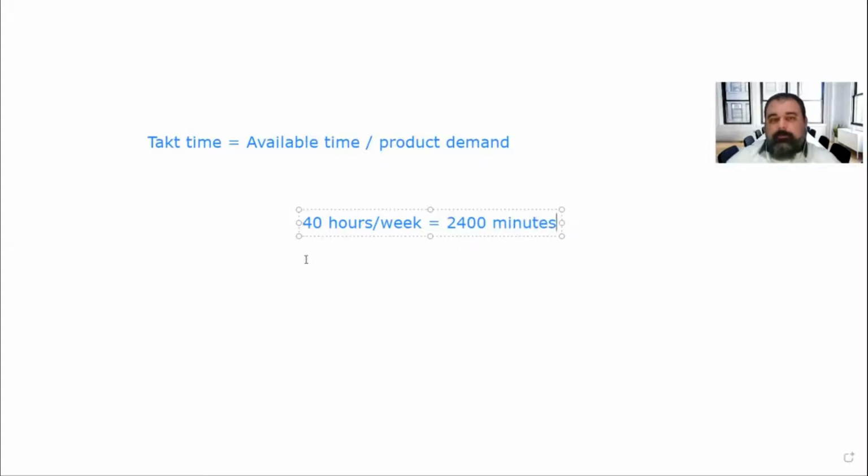And if your product demand is about 1,000 products, I'll call them units, per week, then what we'll have is 2,400 minutes divided by 1,000 units. Each unit should be produced every 2.4 minutes.